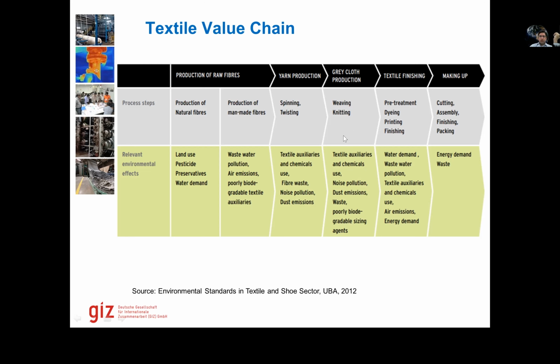to the weaving process. Then we come to weaving or knitting, where we are producing the cloth, and these are also usually electricity users rather than thermal energy users, except for a few of the processes where we might need to apply sizing or do a de-sizing after weaving if we have a fabric process afterwards. If we don't have a fabric processing unit afterwards, then we apply the size after this to control shrinkage, and then we send it to the fabric mill, which does the de-sizing first.